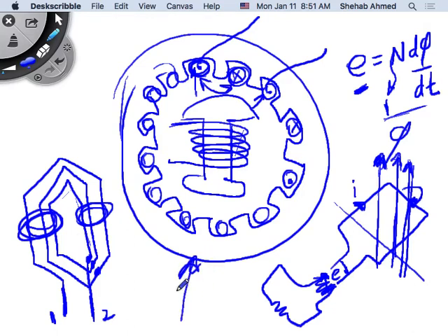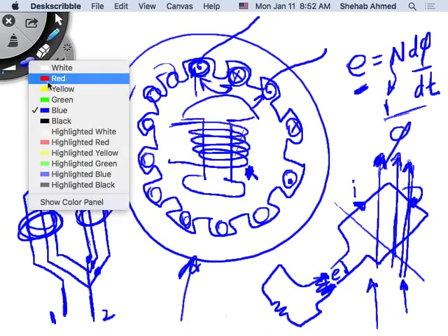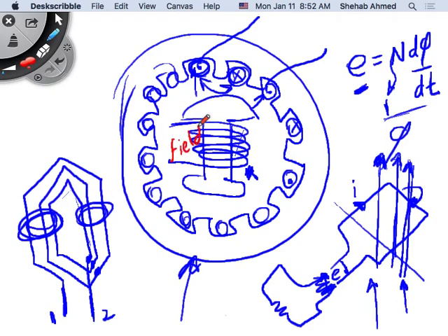This electrical generator that's connected to the mechanical prime mover will turn this basic winding, this single winding. Let's say you have magnets creating this magnetic field, and a prime mover is turning this around, then you will have voltage generated, right? So in this case, the magnets are represented by this winding. This is called the field winding of a synchronous machine. So this is what's creating this magnetic field.